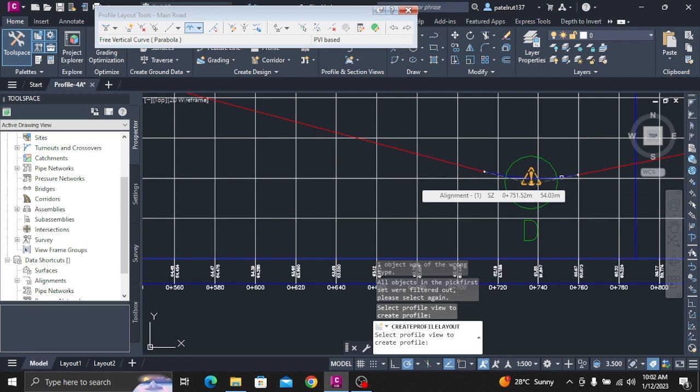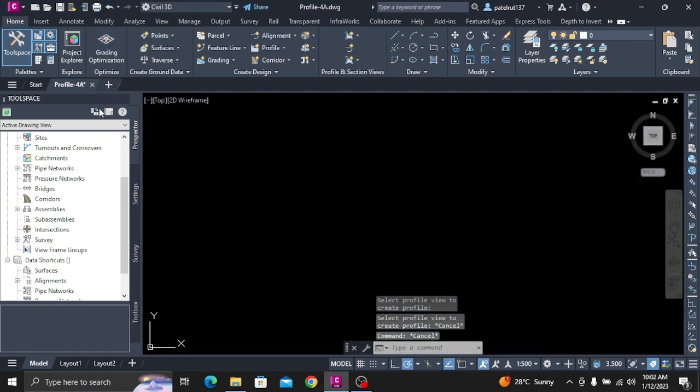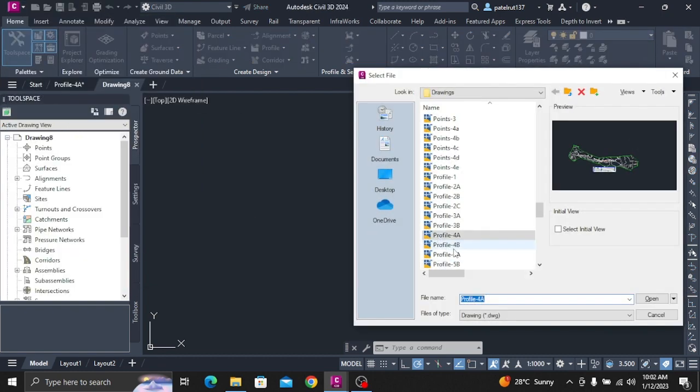In the Select Pipe Networks to Draw in Profile View list, select the Select checkbox. Clear all checkboxes except for the following parts. WE Pipe, 1. WE Pipe, 2. WE Structure, 1. WE Structure, 2. In the Select Stacked view to specify options for list, select Top view.